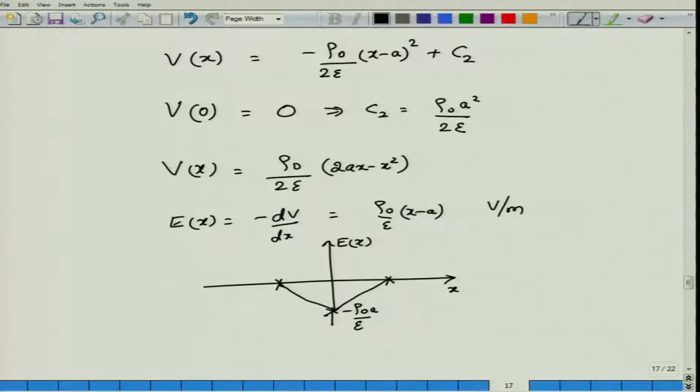And if you were to plot the voltage in the p and n region as a function of x, it will have a linear plus parabolic kind of shape. Far away from the junction it would be saturated, although strictly speaking we have not derived that, but at the center it would be 0 and then it would go something like this.